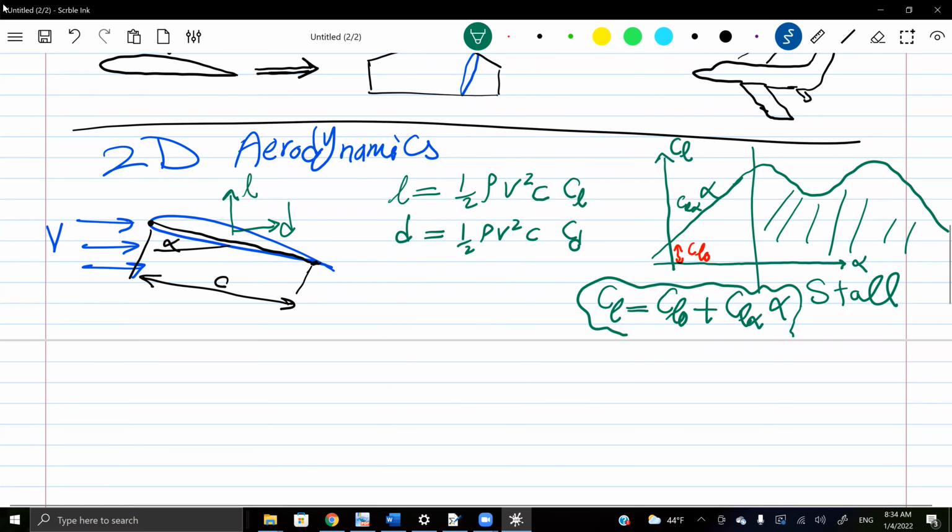All right. CL alpha is the slope, and the slope is simply 2 pi for a flat plate. Every airfoil shape has its own slope. Some shapes have higher slopes, so they have higher capability of generating lift, of course, if they are nicely designed. The airfoil is one of the best shapes. But anyway, if it is not given in that course, you're allowed to take CL alpha, the slope, as 2 pi, all right? CL alpha of the 2-dimensional airfoil.